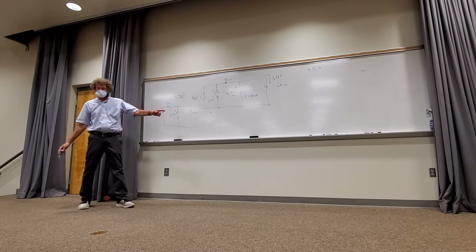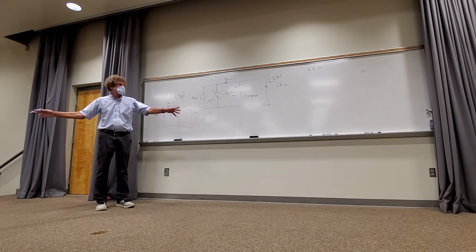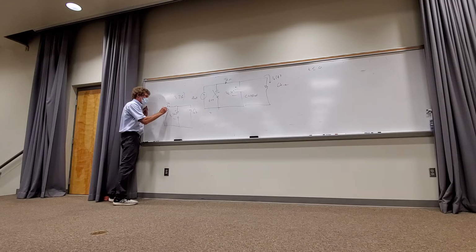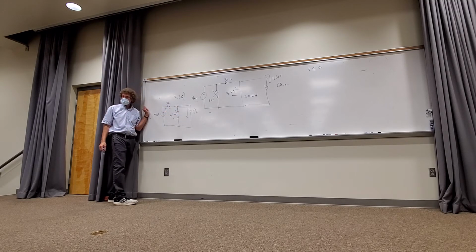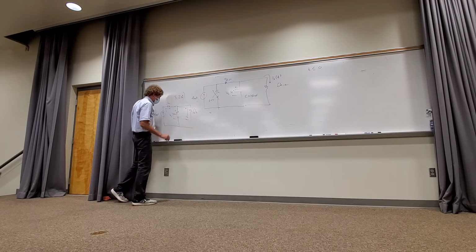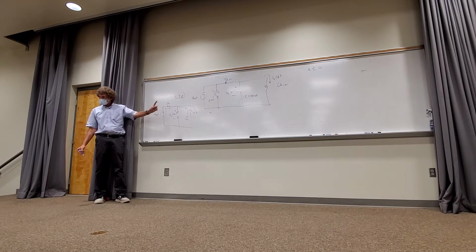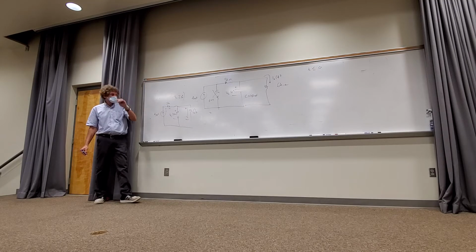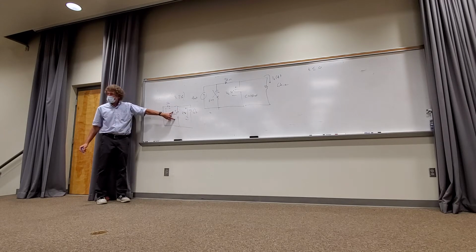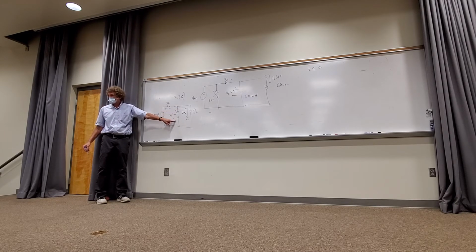So how do I get this voltage? Now, just think about it for a second, logically. It's over here, right? How do I get that voltage? All of that current must flow around, right? What's the voltage on this 6K then? 4 milliamps times 6K is 24 volts. Is that class? How many see this? So this is 24 volts. How many see that 24 volts is exactly VC? It's exactly across these 2 points, isn't it, class? Y'all see it? In the back there too, guys? Can y'all see it? It's very obvious.